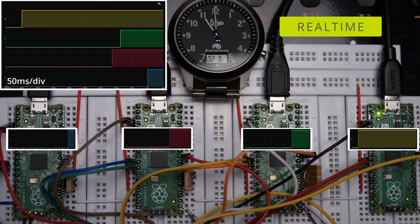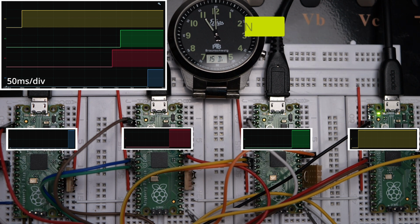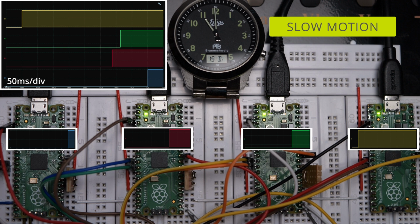After 24 hours, the drift of the rightmost Pico got so large that the trigger point of the logic analyzer had to be moved from 50% to 90%. With a now established yellow, red, green, blue flashing sequence, the eye does not get an artificial impression of motion anymore. The rightmost yellow Pico has drifted 400 milliseconds from the leftmost blue Pico, so it is approaching a point where it flashes exactly opposite to the leftmost board.